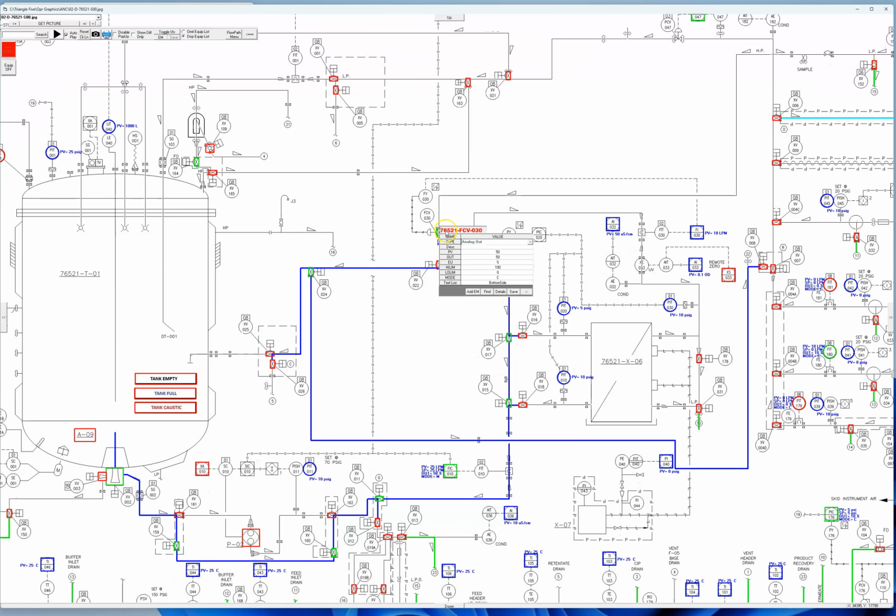Over here you got analog out. You can change the configuration or you can change the PV. In this case, let's set it to 0. Oh, sorry, set it to 0. And I hit OK. For that to take effect, you had to hit save. So you then update here, or you can change, let's say, the mode.